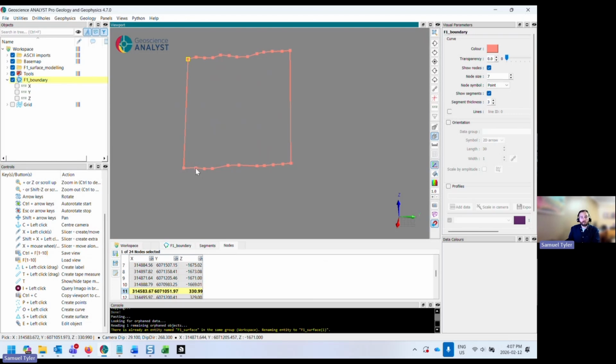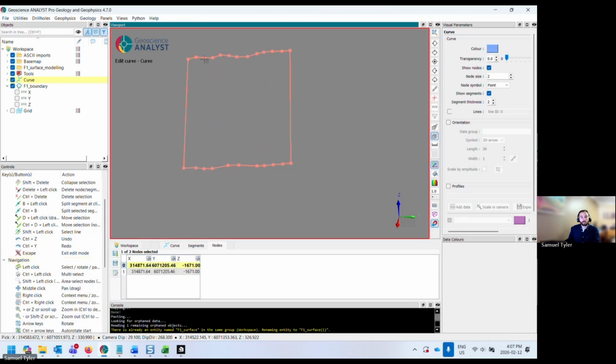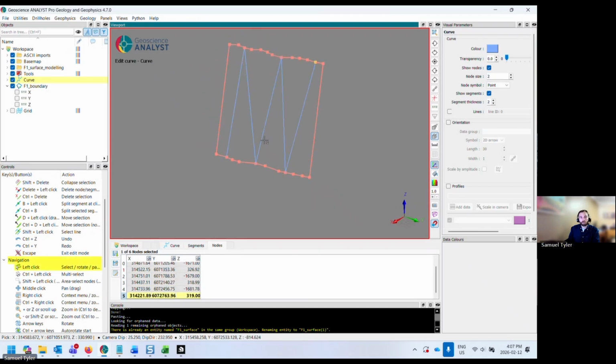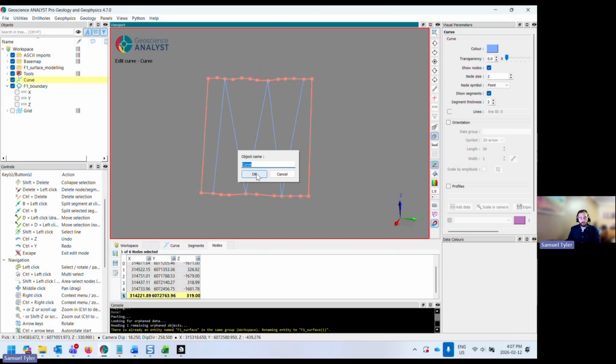And then press O to start snapping some lines just like that to lace up the insides. Doesn't need to be overly dense. It's actually probably better the less dense it is. We're just doing something rough. Then once you're done with that, press escape.